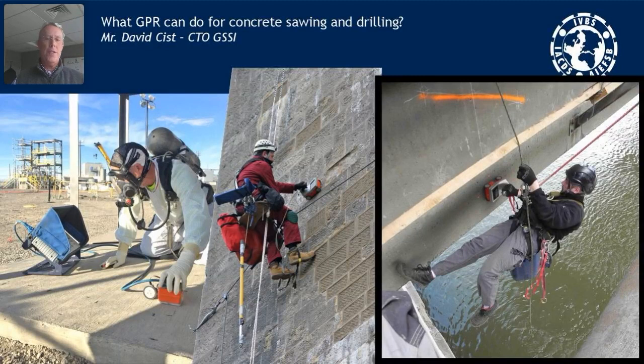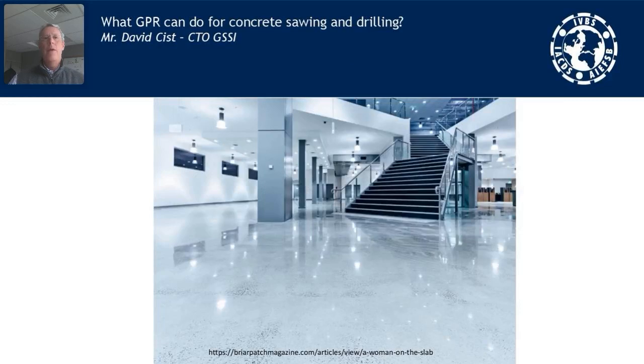So when you look at this floor, for example, you walk onto a job site and you look at a floor. What are you doing? Well, if you're like Brett and like me, you're always trying to figure out what's down there, what you can't see. So you might grab the as-built plans if they exist. For old buildings, that's impossible. You might do a walking inspection looking for junction boxes. You might go under the floor and look at the ceiling, the underside, if it exists. And then you're going to cut.